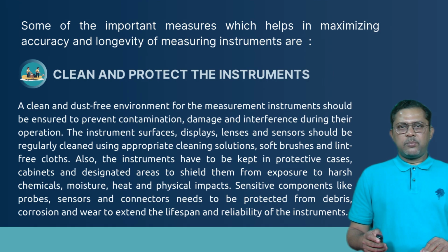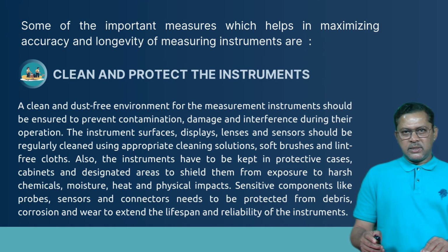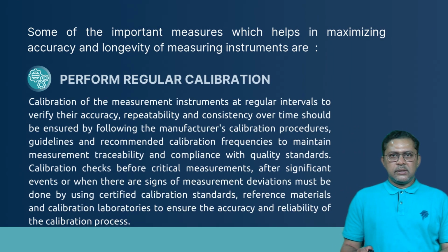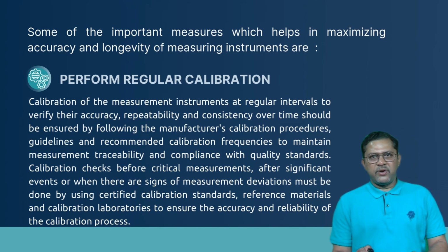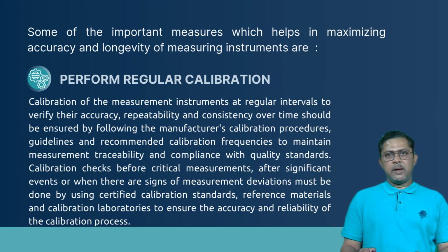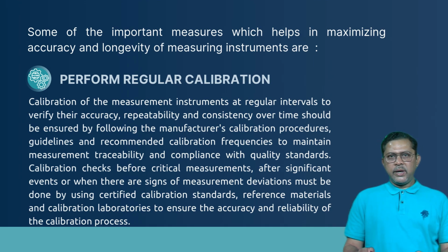Sensitive components like probes, sensors, and connectors need to be protected from debris, corrosion, and wear to extend the lifespan and reliability of the instruments. Number 3, perform regular calibration. Calibration of the measurement instruments at regular intervals to verify their accuracy, repeatability, and consistency over time should be ensured by following the manufacturer's calibration procedures,